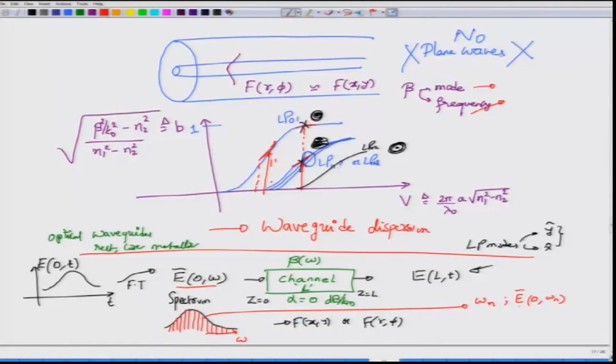Why do I say it is a complex amplitude? Because you know that E0(omega) is a complex quantity, which means that at every frequency component omega n, you have to give both the magnitude of the complex amplitude as well as the phase angle. Consequently, you have a magnitude spectrum and a phase spectrum, which simply tells you, given a frequency omega n, what the magnitude of the complex amplitude is at that frequency and the phase of that component at the same frequency. So, that is what I mean when I say this is a complex amplitude.